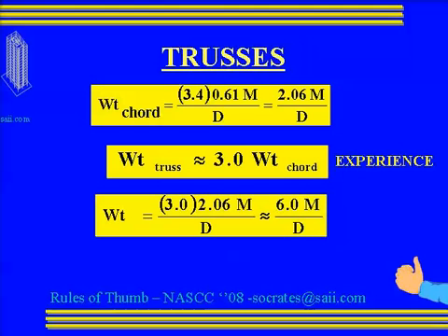And the weight of the cord, truss strip 3.4 again, that we talked about, gives you approximately that the weight of the cord is 2 times the moment divided by the depth. This is purely from my experience. Approximately, if you already know what the weight of your cord is, the total truss is going to weigh 3 times that weight. Essentially, you have 2 cords, and all the webs, if they're designed in some logical fashion, end up being 1 more time.